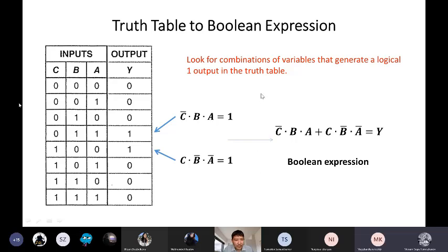Because it means that we have one table that outputs all ones but one zero. Then we will need to just add them. Yes, in this case you will write this kind of combination, then write down plus, but plus means OR. So you need to OR all of the combinations. If all of them are 1, how many will you have? Seven such combinations with output 1.